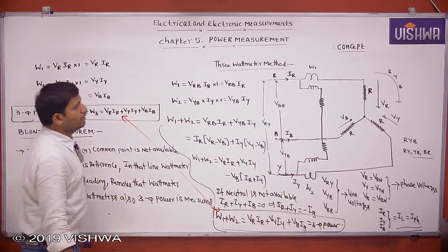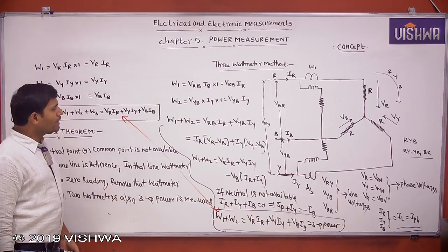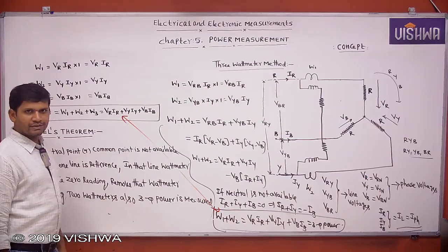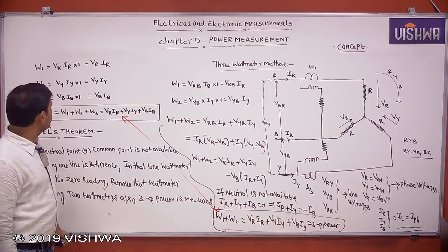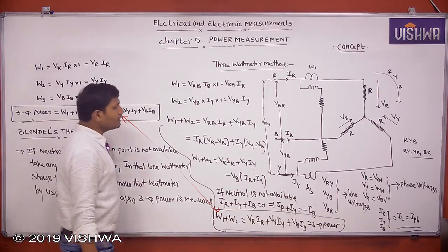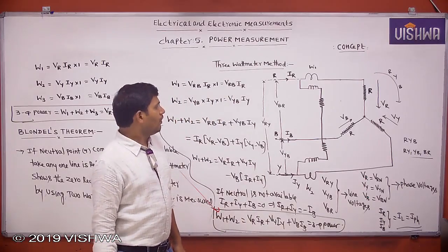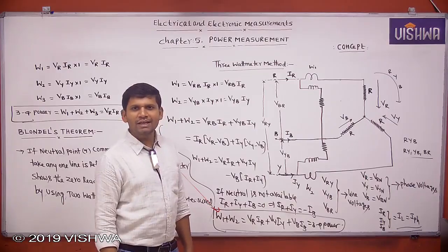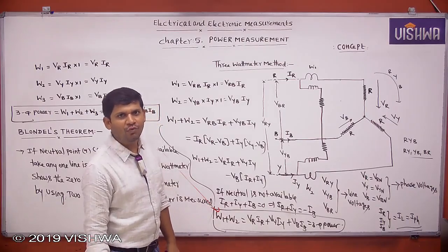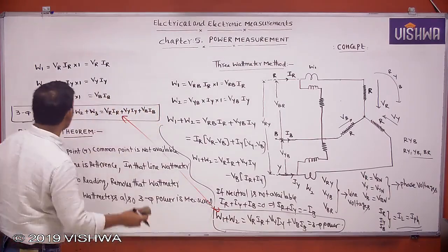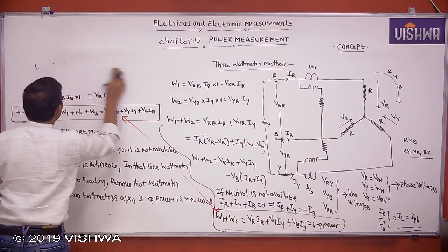Yes, this is how to measure the power using 3 wattmeters. But according to Blondel's theory, there is one statement. For an n-wire system, how to select the number of wattmeters to measure the power. This is according to Blondel's theory that I am giving.